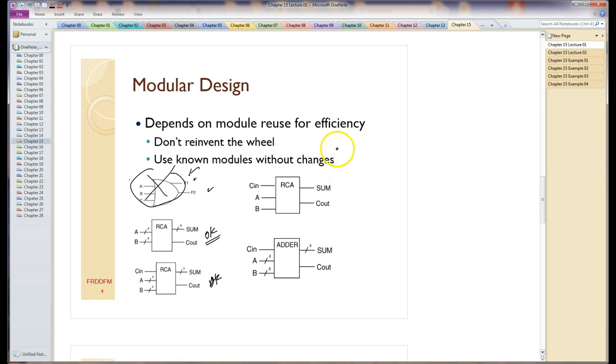Here's a circuit that looks like a ripple carry adder, but it's a mystery because I know ripple carry adders generally have bus inputs here. This one doesn't. When you read this, you think, did the person make a mistake and not put the bus bars in there, or did this person really want a 1-bit ripple carry adder?